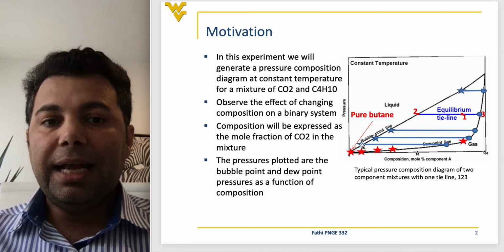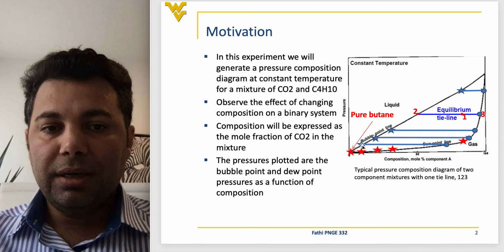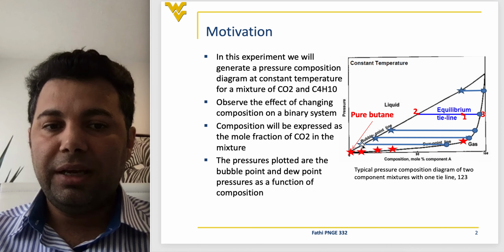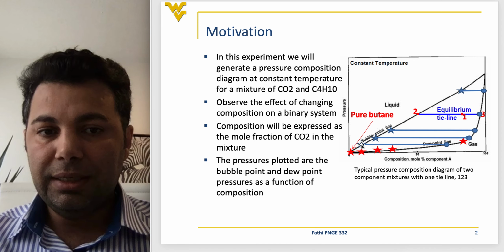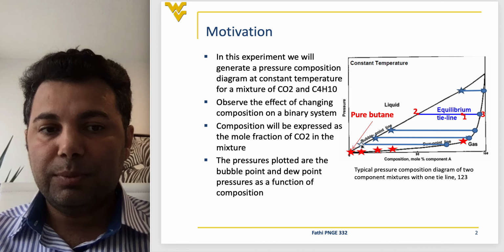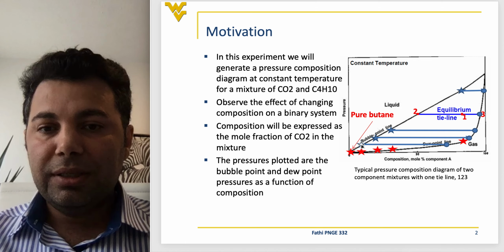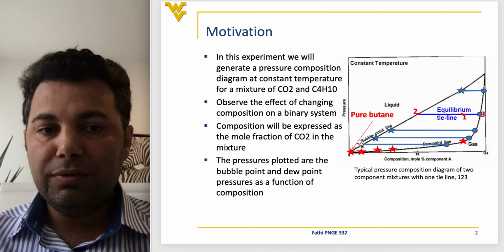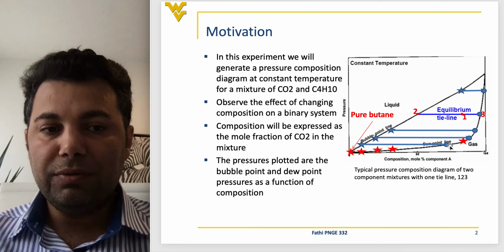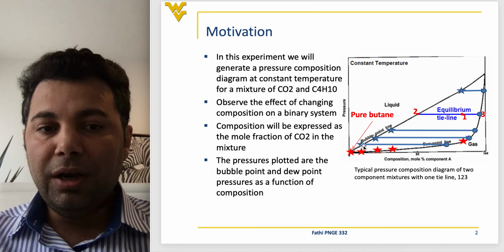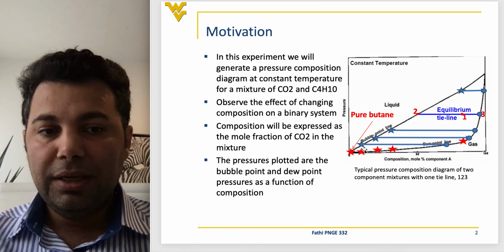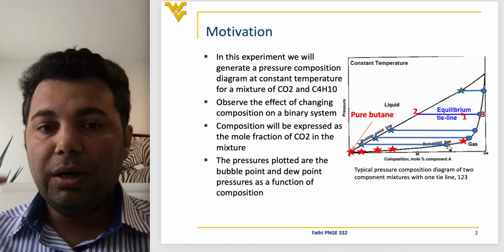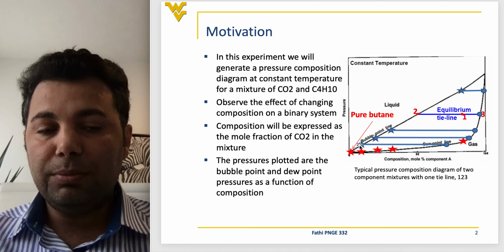Okay. At that point, I can use the gas chromatograph and find the composition of the saturated liquid. It's going to tell me the composition of the liquid and the composition of the gas. So I can find the percentage of, let's say, component A in the liquid phase and component A in the gas phase by performing the gas chromatograph at the bubble point.